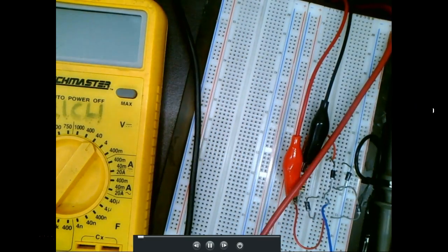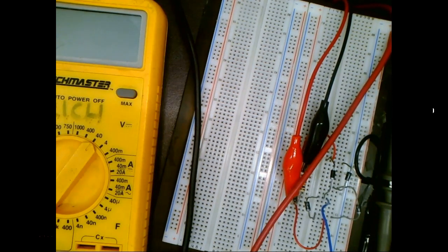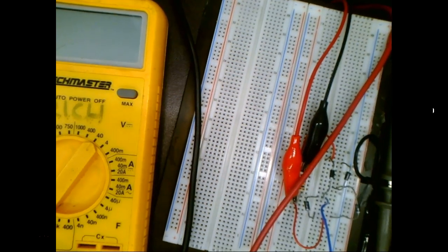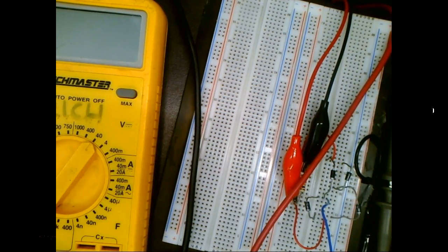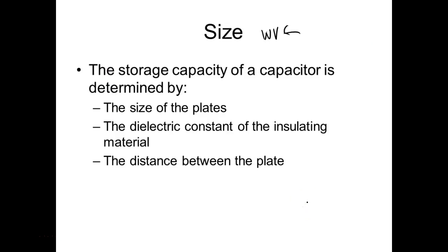On the radial leads, they don't identify both leads, because if they identify one, hopefully you know the other one is the opposite polarity, right? For some reason, on the radial leads, they identify the negative lead, and on the axial leads, they identify the positive lead. You know what we mean by radial and axial now, right? What does that mean? This is a radial lead.